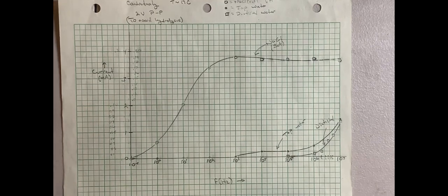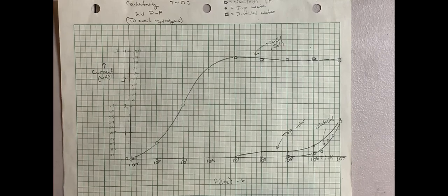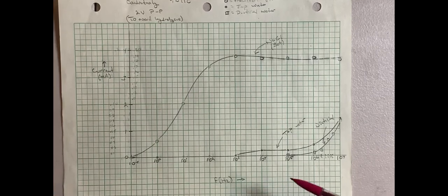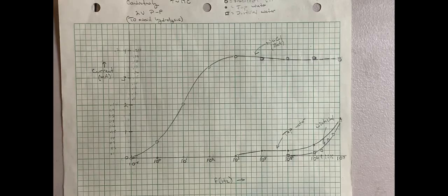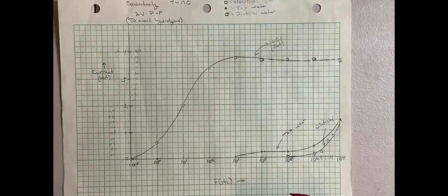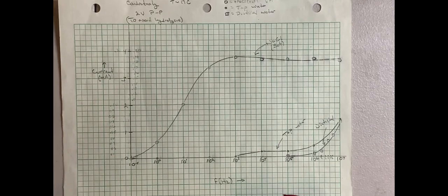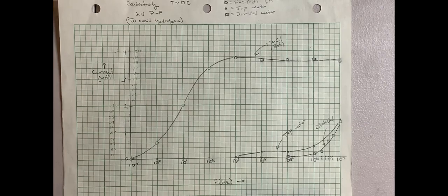There's a thermodynamic driving force for purified water to combine with other substances, such as atmospheric gases. In my test, I discovered that an open beaker of distilled water will give higher conductivity after sitting overnight. And this is because of absorption of atmospheric carbon dioxide, which decomposes to carbonic acid and introduces ions to the liquid.